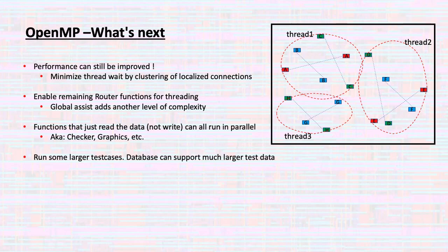Oh, that's a good point. Yeah, so that's basic routing 101. It's something we've learned from building routers. You always want to start with long nets to short nets. We have an option in our router if you want to try short nets to long nets.